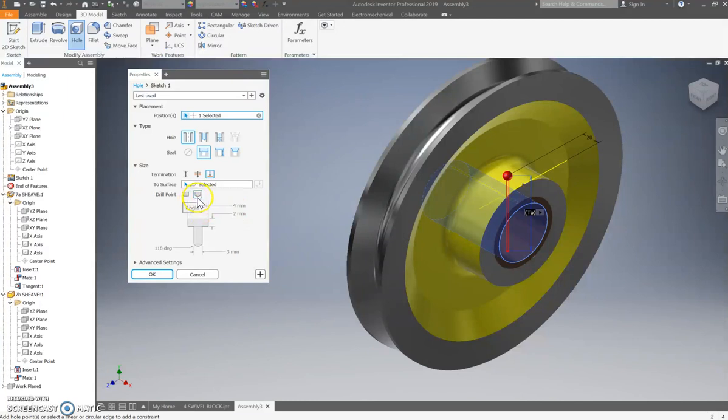Now then, the sizes of the hole. What are we drilling? We're drilling with a drill. That's fine. How big is the diameter of the top of this thing? Well, looking at my little plan here as I turn it over, it's going to take an M12 thread. Let's make that hole 10.5. The reason I say 10.5 is we're going to use a 12 by 1.5 millimeter thread, metric thread.